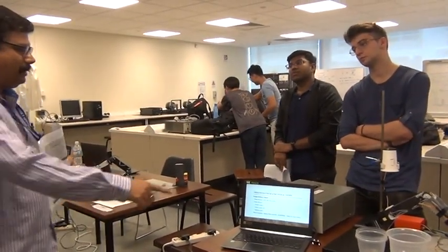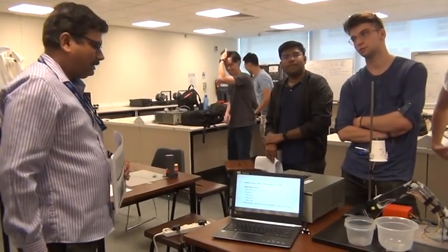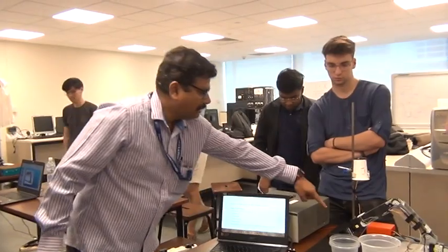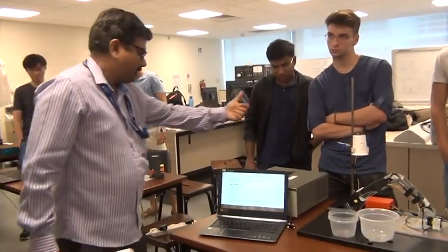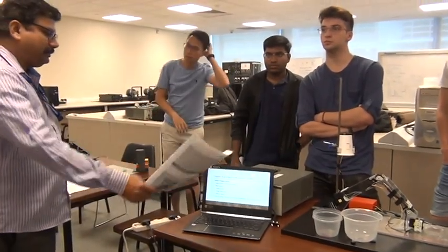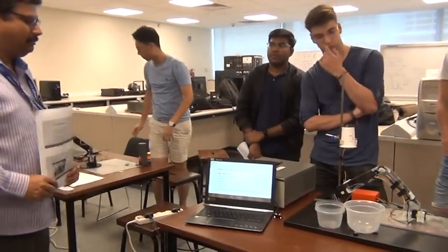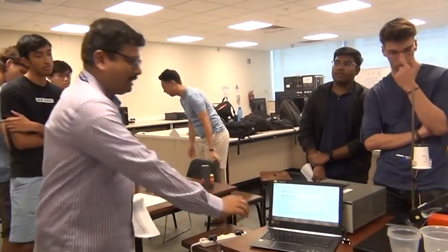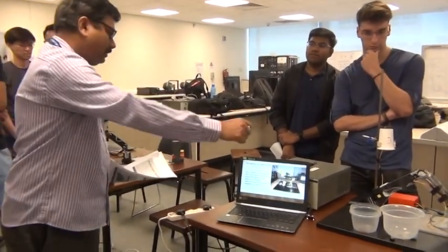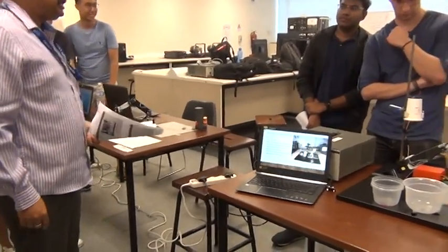Okay, the design of the robot system. The robot actuator is powered by 4 different motors, and we have a contact sensor here, and we have a color sensor and a distance sensor, and the controllers are an Arduino microcontroller and Dynamixel with Python software to control the servo motors. Okay, motor 1, the base motor, provides horizontal plane rotation.